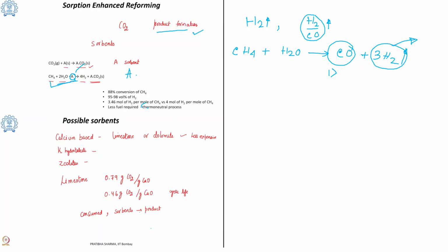It will adsorb the carbon dioxide produced in the reactions, after the water gas shift reaction, where carbon monoxide is converted and produces carbon dioxide. If we absorb this carbon dioxide gas, the overall rate of reactions will be high. That's why one adsorbent is used to absorb this carbon dioxide gas.